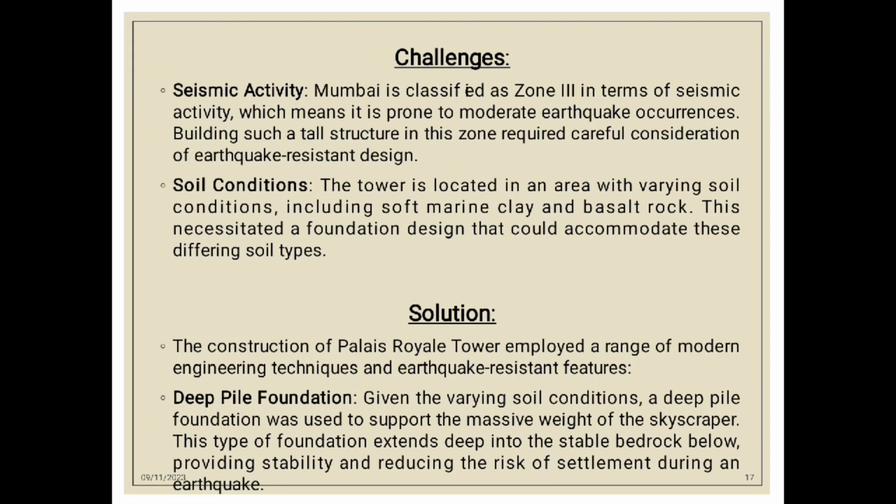Challenges: seismic activity. Mumbai is classified as Zone 3 in terms of seismic activity, which means it is prone to moderate earthquake occurrence. Buildings such as tall structures in this zone require careful consideration of earthquake resistant design. Soil conditions: the tower is located in an area with varying soil condition, including soft marine clay and basalt rock. This necessitated a foundation design that could accommodate these different soil types.